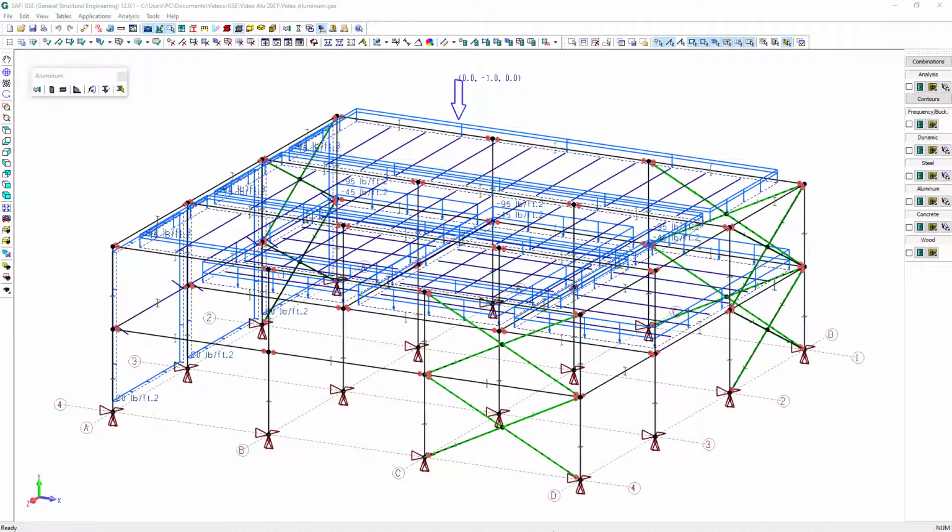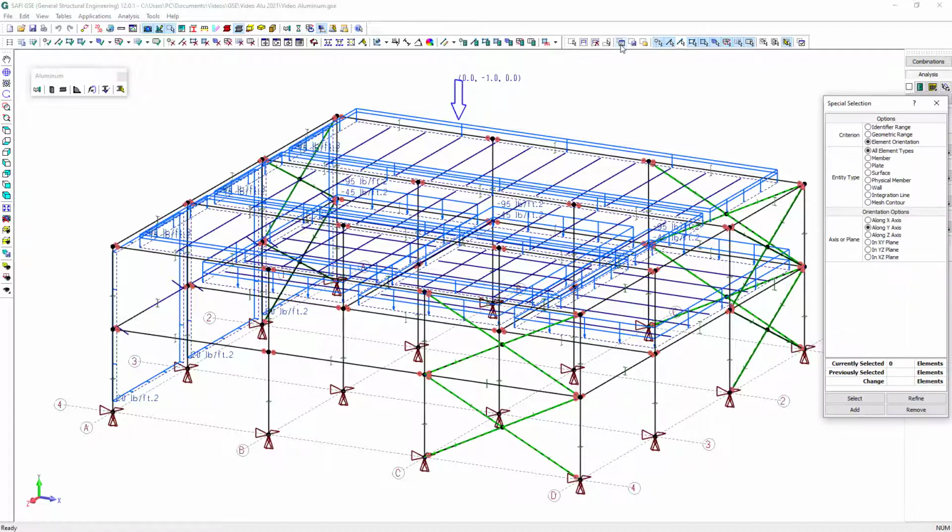We are now ready to define the welds. The influence of the welds is defined by specifying the ratio of welded area on each flat segment of the sections. In this example, we assume that only the columns have welds.